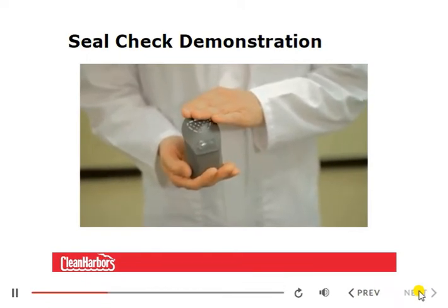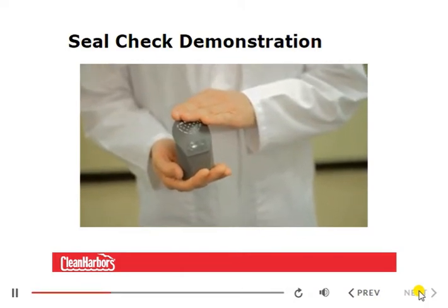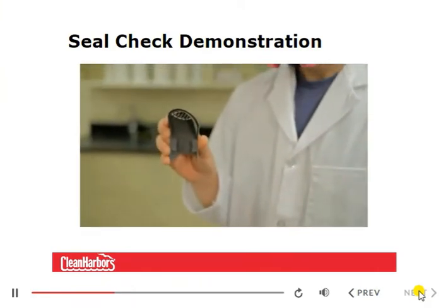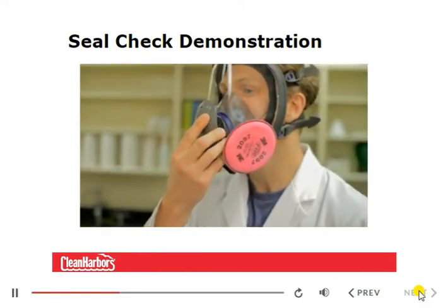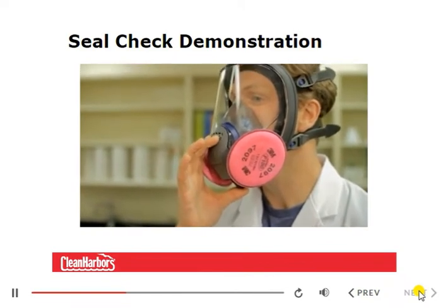You can do this either by reversing the removal process you just completed, or simply hold the exhalation valve cover on the sides even with the notches on the two tabs on the inside. Then, contact the ridge of the lens on each side of the exhalation valve assembly with your fingers holding the valve cover. Slide downward until the valve cover snaps in place, and you're done.